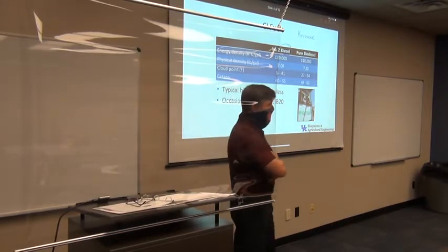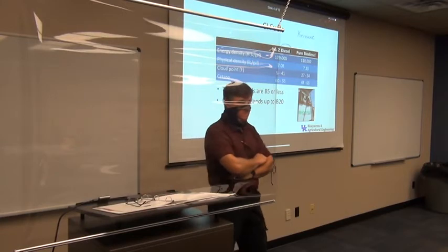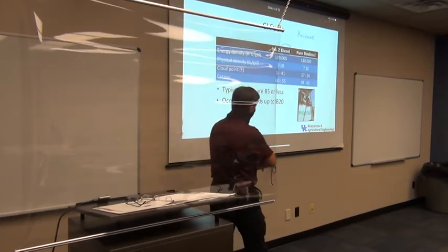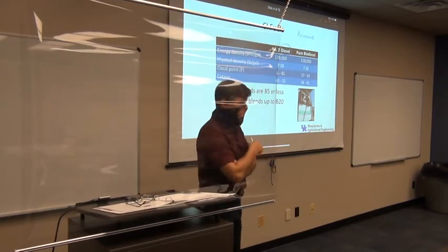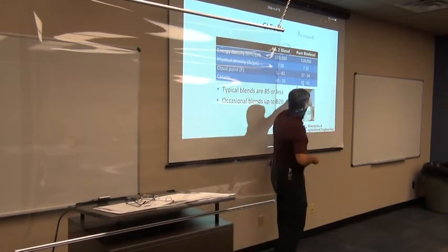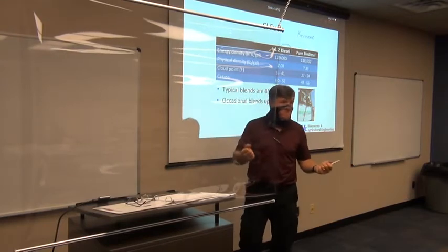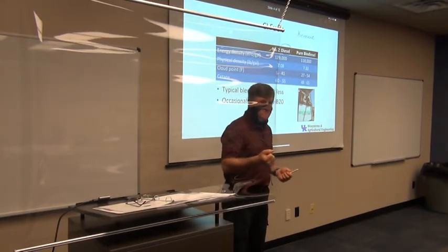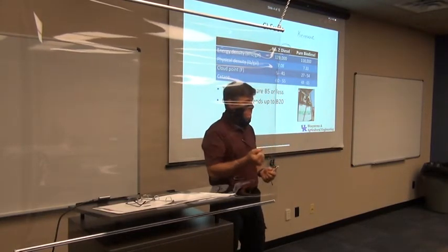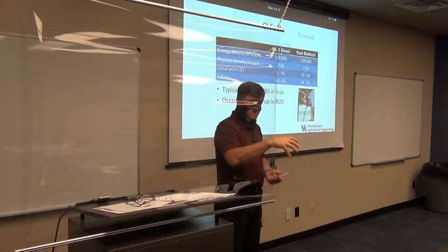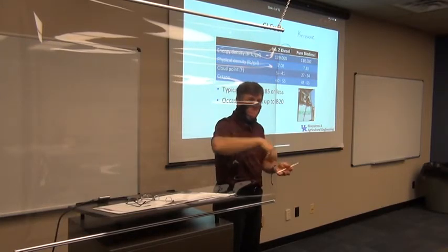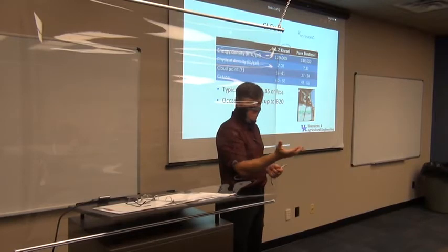Look at the difference in the biodiesel at the cloud point. There's a huge range. This is degrees Fahrenheit. That biodiesel will gel up at a fairly cold temperature. So think about cooking oil. Have you ever taken cooking oil camping? Has anybody gone camping in the wintertime when it gets cold? And what will happen to your cooking oil sometimes? Have you ever had it turn into something like Crisco, shortening? That's what it'll do. Cooking oil will actually turn into the consistency of shortening.